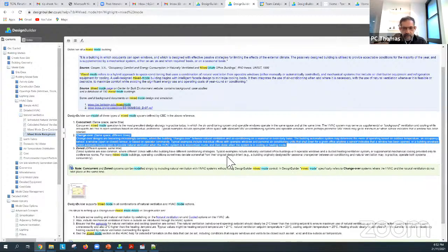And in some ways, I would say pick even a week when you know mixed mode will work and do your diagnostics on that week, because then you can see very quickly, the simulation runs are fast. You don't have a lot of data, so you can graph it all and look at it very carefully. When it's working well, then you can turn off all the surface variables, because otherwise you'll get this huge file, and then you can run it for the year.